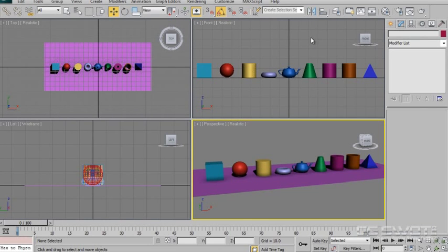Today we're going to take a look at some very basic modeling techniques in 3D Studio Max. I got a few emails from people that haven't used 3D Max before and wanted to know where to start when modeling is concerned. So what I thought I'd do is something based on primitives. We're going to build a little scene in a moment, and it's just going to be a very simple snowman scene, and we're only going to use primitive objects.